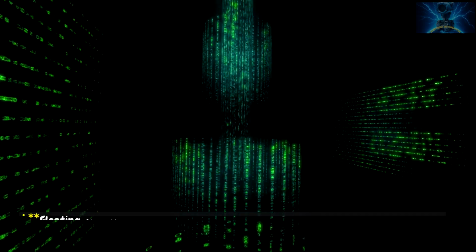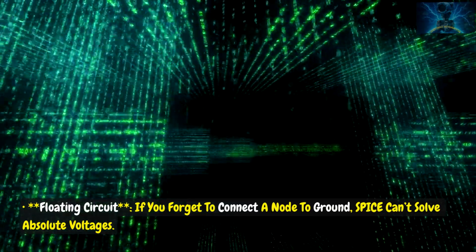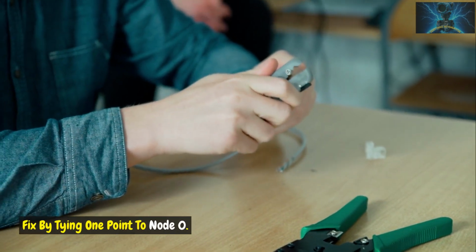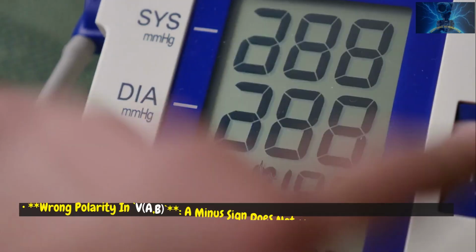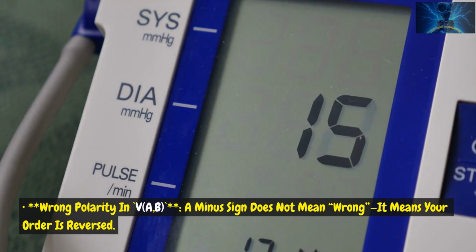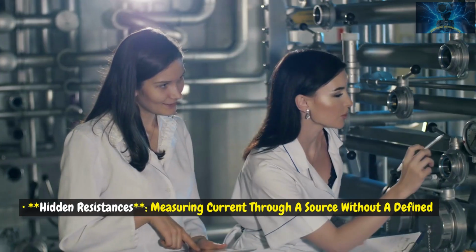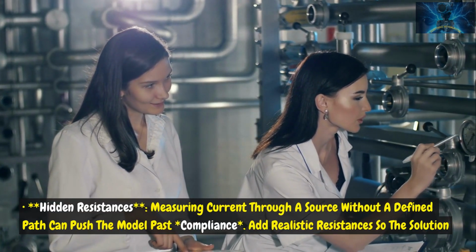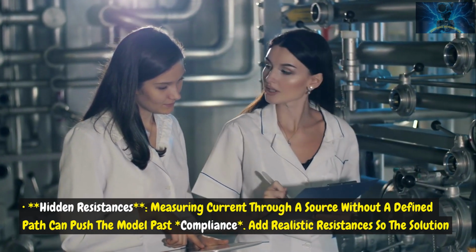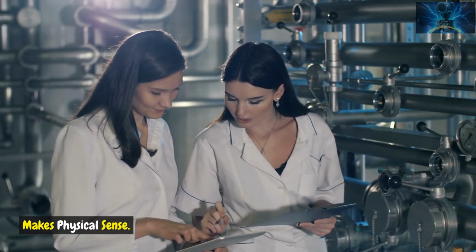Common gotchas. Floating circuit: if you forget to connect a node to ground, SPICE can't solve absolute voltages. Fix by tying one point to node 0. Wrong polarity in V(A,B): a minus sign does not mean wrong. It means your order is reversed. Hidden resistances: measuring current through a source without a defined path can push the model past compliance. Add realistic resistances so the solution makes physical sense.